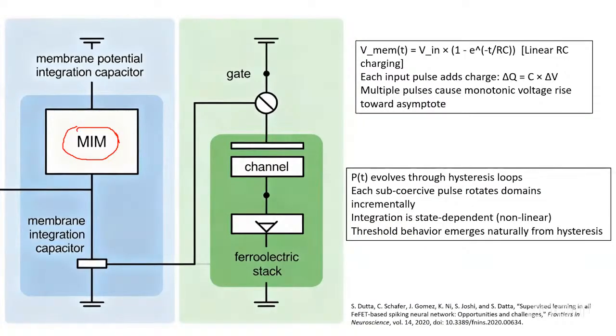Now, if you use a ferroelectric FET, then the channel conductance can be modulated with the gate itself. And if you can tune the gate, then you can tune the channel. So basically, you can control the channel through the ferroelectric gate. We can say the ferroelectric layer in the gate stack.